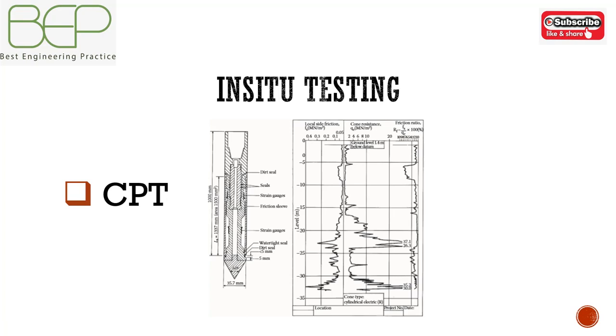A pore pressure sensor may also be used, and it's typically fitted between the cone and the friction sleeve. The force applied to the cone as it is pushed into the ground may be measured mechanically or electrically. Wherever possible, an electric cone should be used.